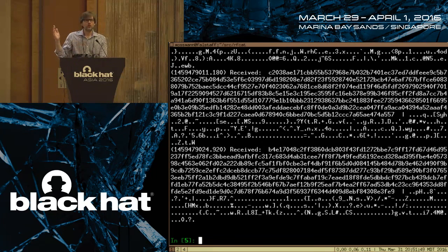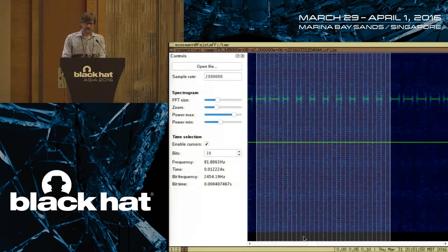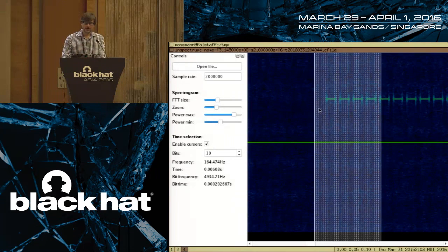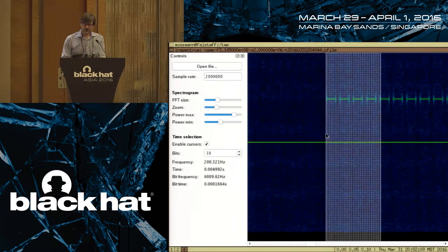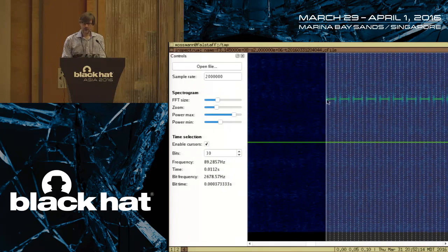So it's expecting to see on, off, on, off, on, off, on, off, or 1, 0, 1, 0, 1, 0, 1, 0. And we don't actually have that. If we look back in Inspectrum, at the beginning of a packet, what we had was not 1, 0, 1, 0, 1, 0. What we have is, in fact, well, I don't have this quite set up right, but what we have is 1, 1, 0, 1, 1, 0, 1, 1, 0. We have a waltz instead of a two-step. And that is not going to satisfy the Yardstick 1's notion of what a preamble looks like.